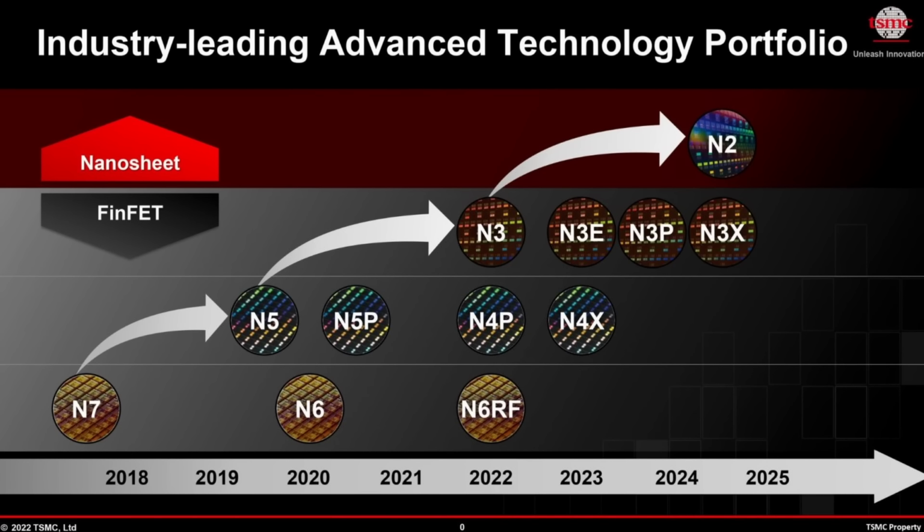And I'm not talking about the electrical drawings. I mean real-world implementations based on transistors of the specific node you selected. They are all part of the process node development kit and are commonly called standard cells. There are so many of them that there is even a standard cell library. When someone talks about libraries related to process nodes, that's what they are talking about. It's literally a huge library of pre-designed logic gates to choose from. What a great customer service. I'm guessing that's why foundries are so expensive. But it gets even better.